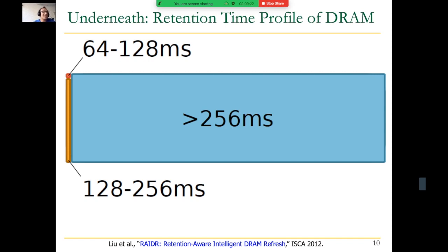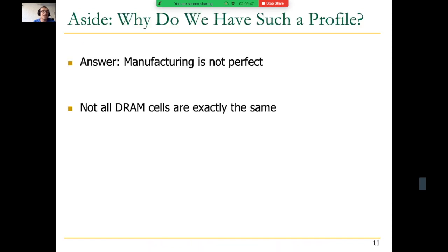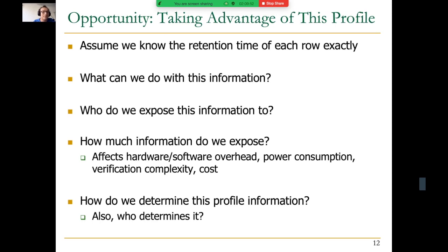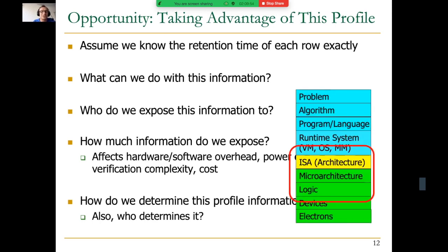And the operating system can tell the memory controller, I'm guaranteeing you this. Now please reduce your refresh rate to every 256 milliseconds. That way you're guaranteed, hopefully at the software layer, if your information is correct, that you're never going to need a refresh more frequently than every 256 milliseconds. So that's another powerful benefit of co-designing across the stack, as you can see. That was proposed, by the way, in a paper that we may actually look into also.